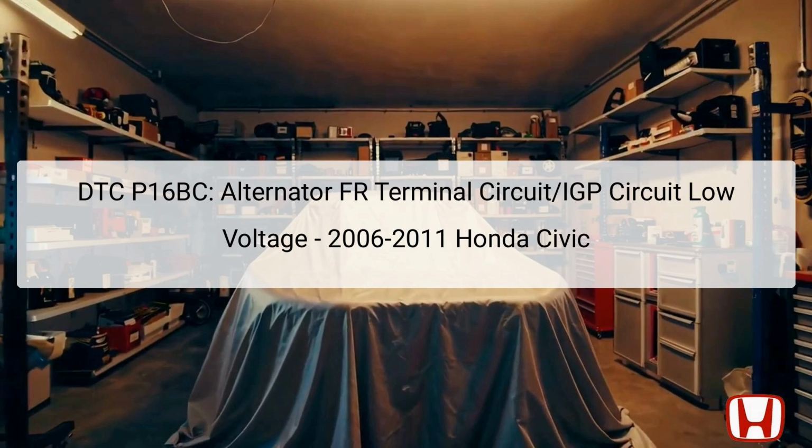When troubleshooting this DTC, it is vital to gather all available freeze data and onboard snapshots, which provide valuable information about the vehicle's operational conditions leading up to the code setting. Understanding this background information is essential for accurate diagnosis and repair. The diagnosis will include checking wire connections, terminal conditions, and other related components, all essential for maintaining the vehicle's electrical